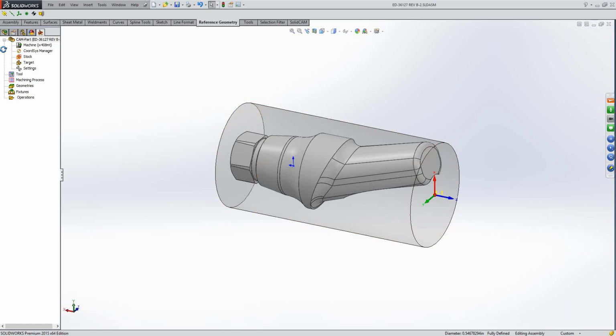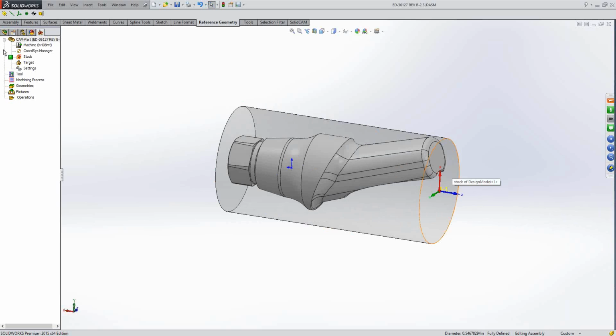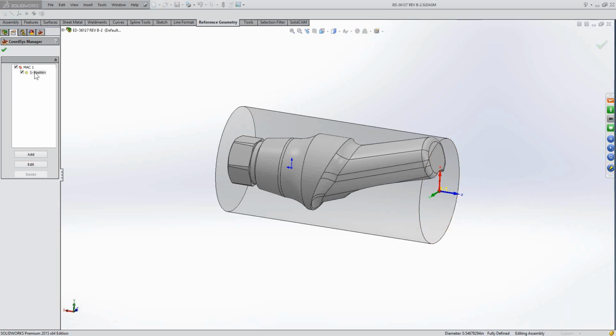Let me show you why I select this cylinder. First, in the next process, when I define the setup, I will be able to measure some things. But the main important issue here on a mill turn is that we can work milling on face and on side, radial.